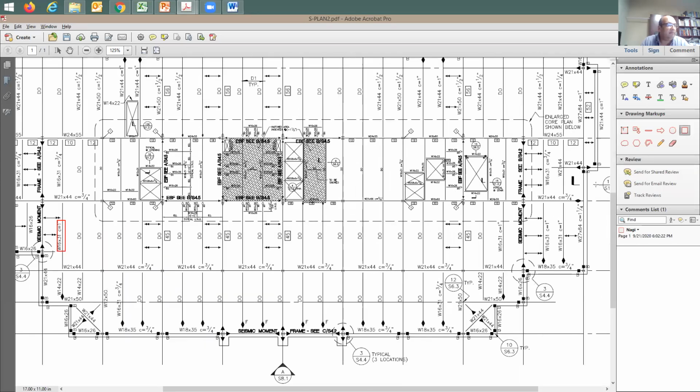Let's give you this beam. They are all simply supported. There is no continuity. So no one would think that we need to design the entire beam here. No. When it comes now to tributary width for this beam, it is going to be half of the way from here, between the other two beams, to here. So this distance from here to there is going to be the tributary width for this beam, or for this girder, if you like.